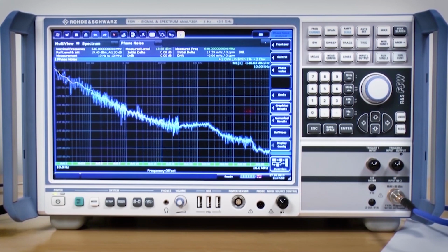One important point to note is that on a spectrum analyzer, the phase noise is measured against the analyzer local oscillator. Any noise on the oscillator will be superimposed on the plot. Therefore, the oscillator should have a noise performance better than the signal being measured by about 10 decibels. Other techniques like cross correlation are present in phase noise measuring systems, and this overcomes the issue, but these systems are normally very specialized and much more expensive.